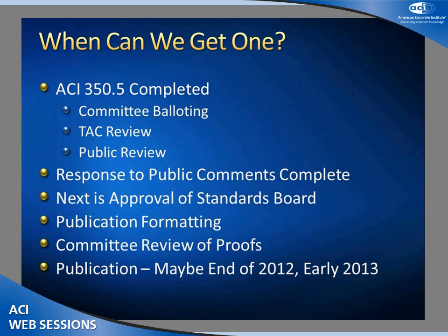You more than likely have to say, this is what we will do for acceptance. I do find in specifications there are times I'll see any cracks will be repaired. And if you have a 2 mil crack, you could be chasing those forever in a structure. When you write your specification, think of what's a reasonable crack size or maybe number of cracks of a particular size that's going to still allow acceptance of a structure. You can have some cracking and really not have long-term corrosion or substantial leakage issues. You don't want to have the one like the picture I showed you, which was a little bit of a pond on the floor. Any other questions?